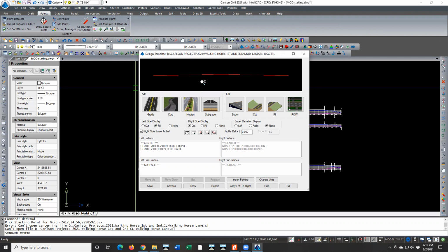And he's either going to dial down his subgrade thicknesses, and that's what a lot of folks did because they couldn't get people to model those subsurfaces. They could only get them to model the finished grade, so they know where they're supposed to be, and they'll dial their blade down. But this gives you the opportunity to do all of that and then output those different surfaces. And I think that one pull down where you can choose the top grade or bottom of subgrade.